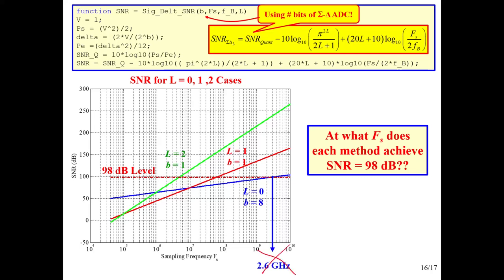Very excessive. How about this one? First order 1-bit A to D converter, 61 megahertz. That's not too bad, actually. For a 1-bit A to D inside the sigma delta, not hard at all to hit 61 megahertz. And what about this one? 4.7 megahertz. Again, piece of cake for a 1-bit A to D converter to be running at that. So that's how these sigma deltas achieve this.